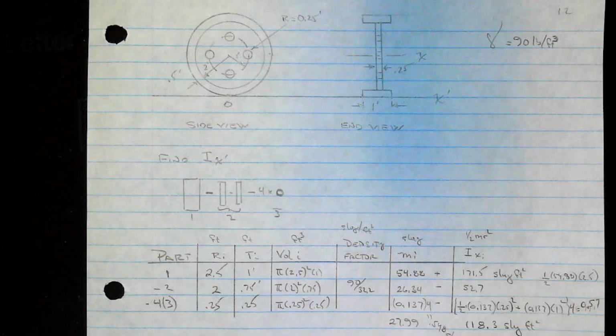Now I've got to convert this into mass moment of inertia. This is a very important point here. We want to make sure we get this right. We need to move these. We're going to compute the inertia at the center of the hole, its centroid. But we then need it to be relative to the center of the overall thing. So we start from its center and we move it to the center of the overall device it's a part of.